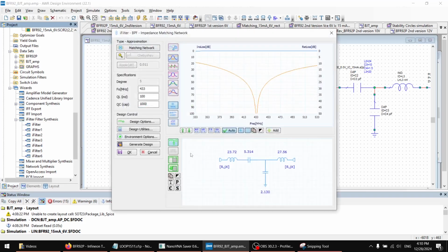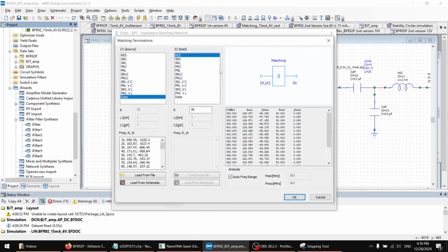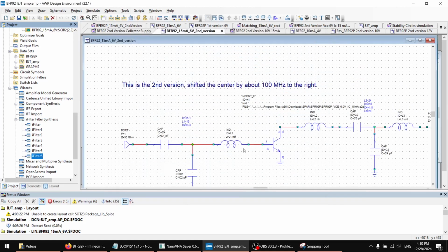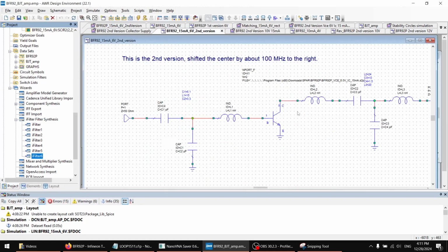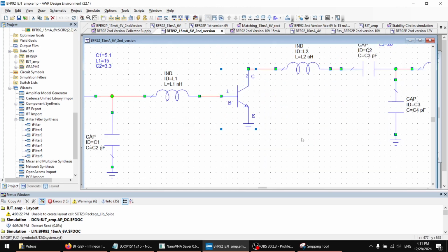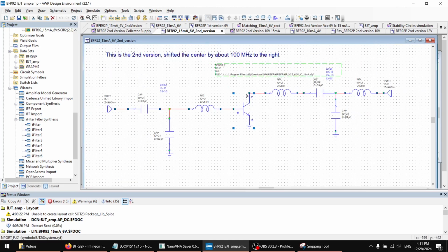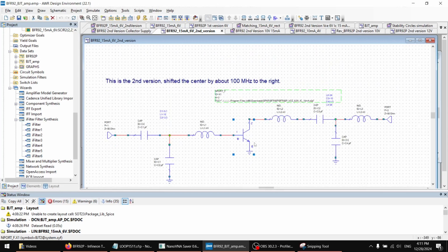And one problem that you might face, here you can see this definition, is that designing one network will load this structure and slightly change the impedance at this port, depending on the isolation of the device. So if you have a microwave integrated circuit, MMIC, or something, the isolation of this will also depend on how this network loads the other port.